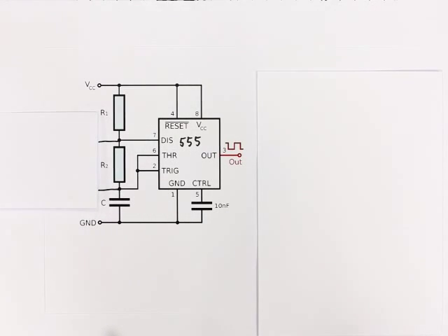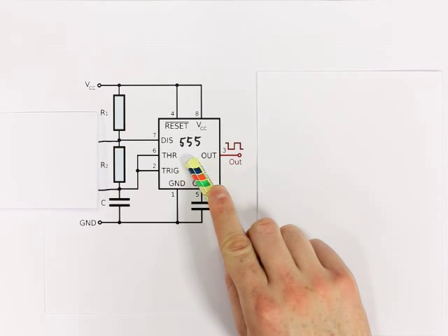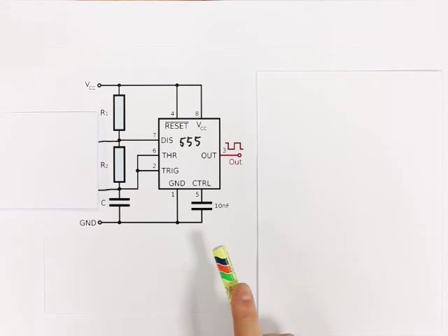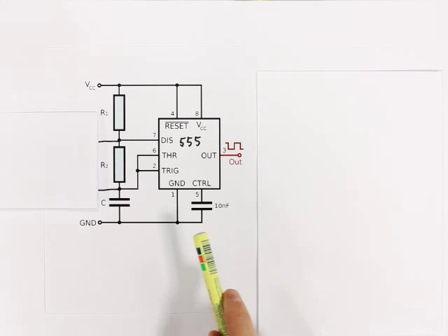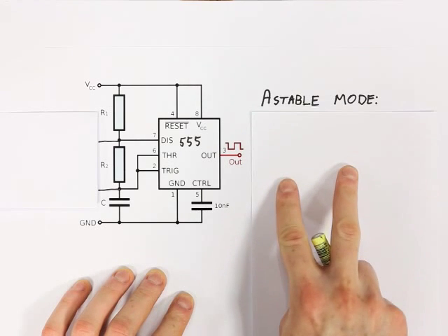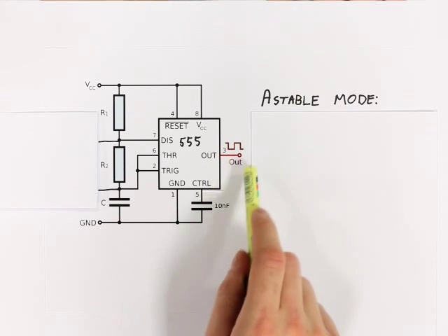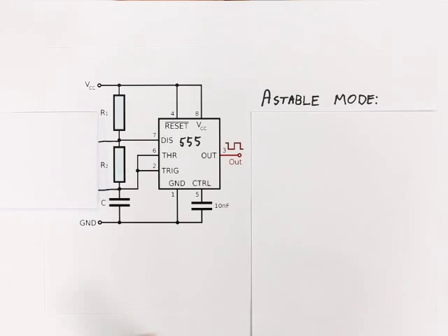Now, the way we're going to achieve our PWM is with a very old, still very common chip called a 555 timer. Professor Agarwal alluded to this device in lecture S25V19, and now you get to see it. So I found this circuit on Wikipedia in the article on the 555 timer, not surprisingly, and this is a circuit for running the device in what is called the astable mode of operation. And that just means it's going to be outputting a continuous series of pulses rather than a single pulse.